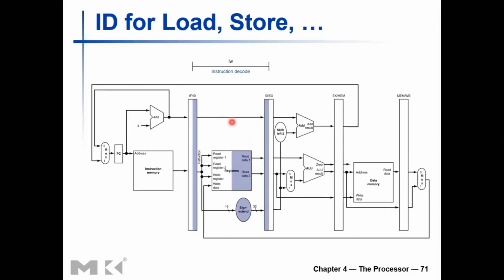So that control unit also happens in parallel to the register reading here, but the time it consumes is less than the time consumed by the register file reading. Right? Register file reading is the dominating operation in this stage. Everything else that happens in parallel, the control unit and the sign extender unit, consume less time compared to register file reading. And all those 3 operations happen in parallel after you get the instruction word from the pipeline register, right? So any questions about this stage?